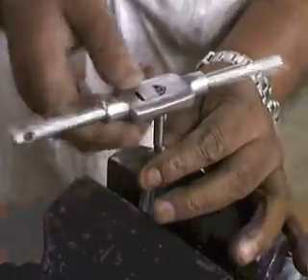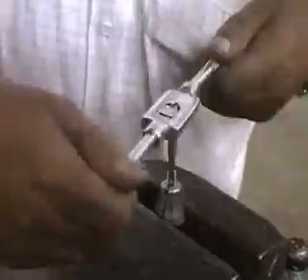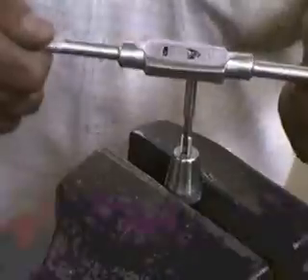The metal of these taps is high carbon steel, hardened and tempered. Last we will put in the bottom tap, which finishes the threads. This is the bottom tap. The procedure is again the same, one forward rotation and half backward rotation. You can see we are moving forward then backward, forward again, backward. You can see how these taps are getting inside the job.